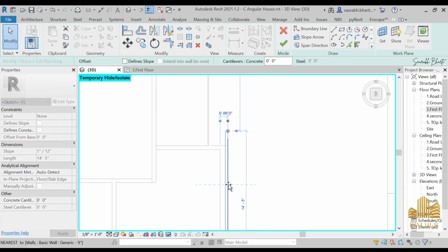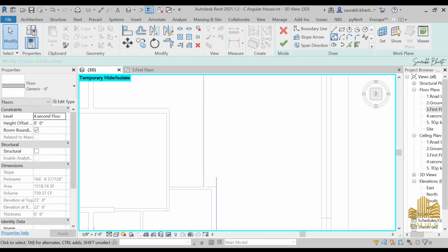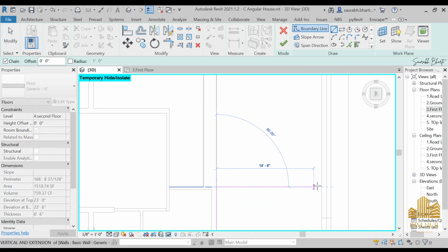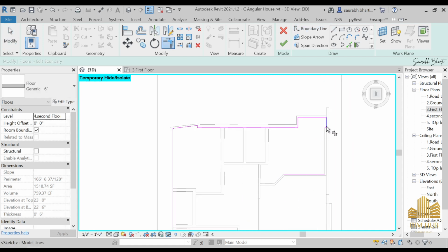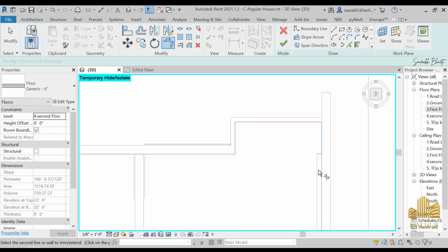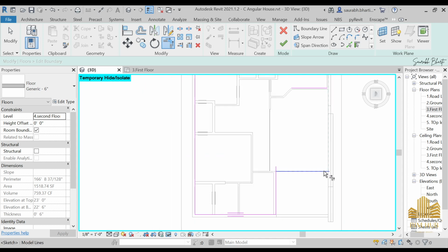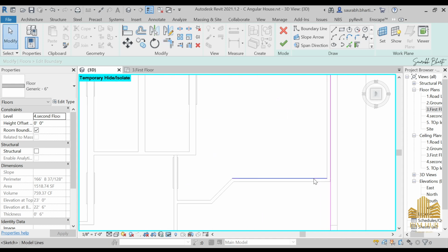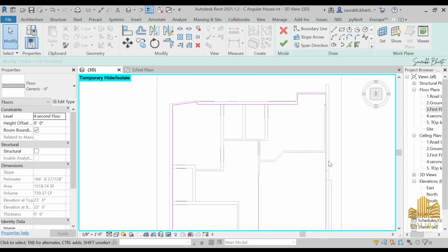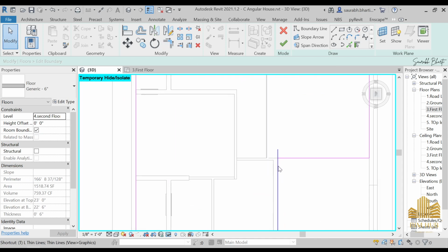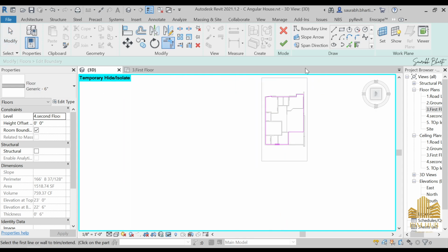And then what we can do is we can take a line from this place to this place. Press escape. TR is the shortcut, and after TR just select this line and select this line and just remove this wall. I will remove this underlines, and now we are done with our flooring part. Just trim this portion, and now we are done.